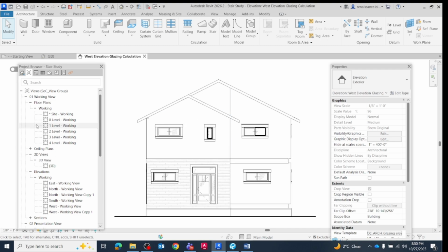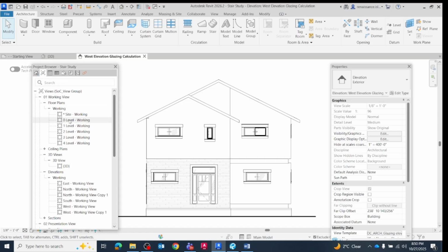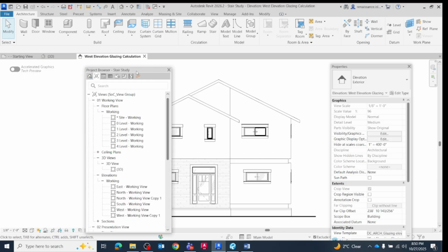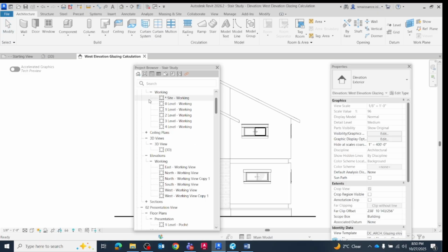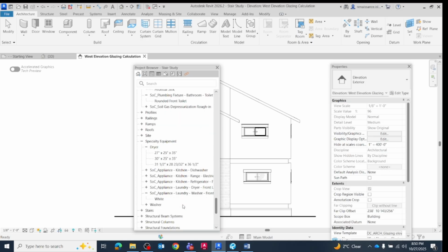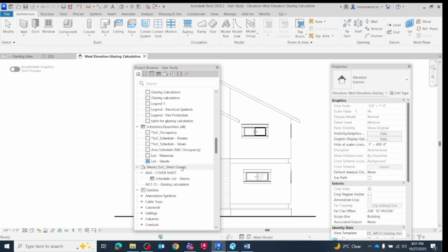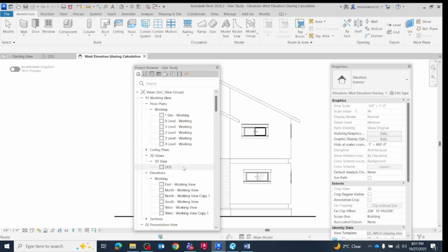Now in Revit, the first thing, as I said, is the different views in the project browser in this template. If you go to the very top of the project browser, this is the home tab. The home tab shows everything that is under the project browser: all your families and different views, schedules, legends, sheets, everything appears. If you want to filter and just see the views, the next option is views. If you click on that, it will show you just the different views.